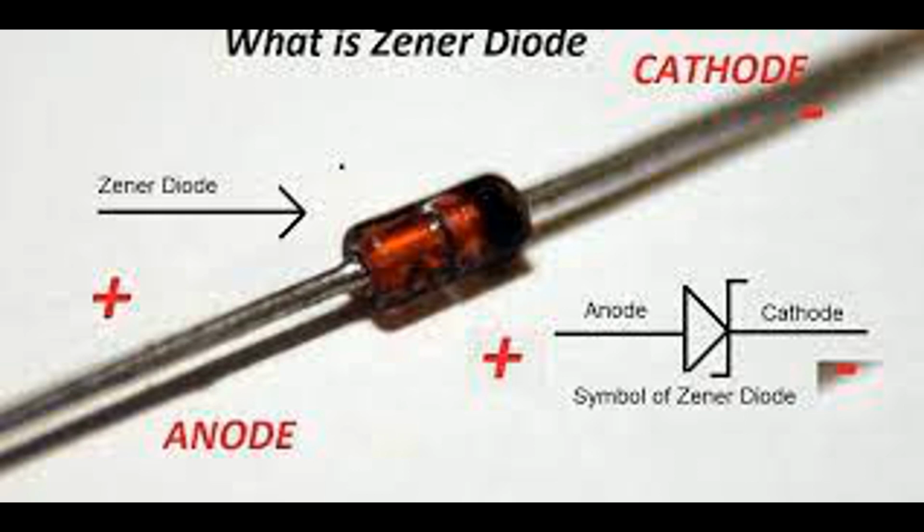Diodes are commonly used in electronic circuits for various protection purposes, safeguarding components and systems from undesired electrical events and conditions. Here are a few key applications of diodes in protection circuits. Reverse voltage protection. Diodes are often used in reverse voltage protection circuits to prevent damage to sensitive electronic components. Placing a diode in series with the circuit blocks any reverse voltage that could harm the device.